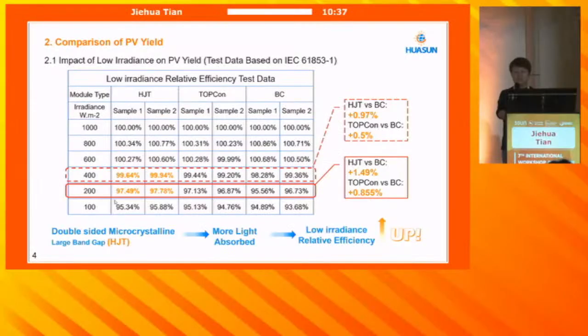Second, simulate the impact of each performance factor on power output using PVsyst. Third, test the power output in 3 environments based on demonstration PV plants. We partnered with 2 third parties, CTC and CPVT, and have built 3 PV plants in the northmost, central, and southmost parts of China, for TOPCon.